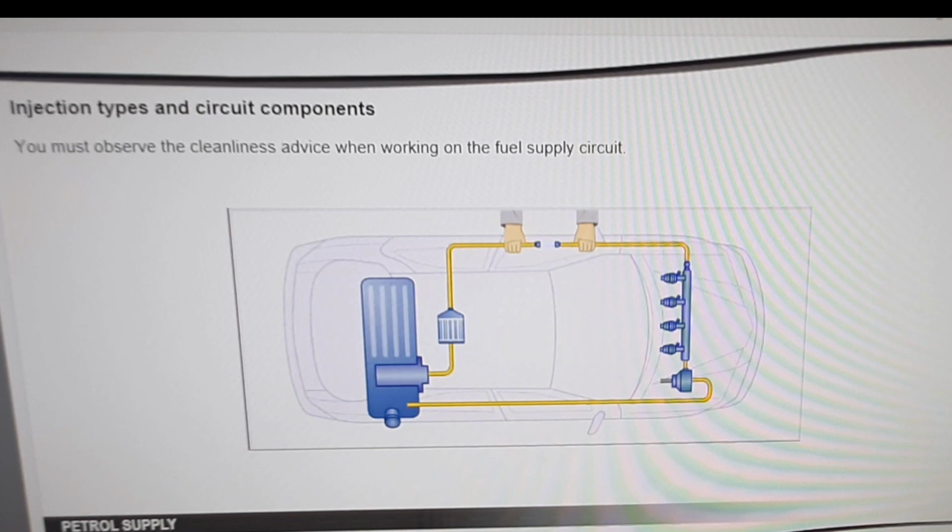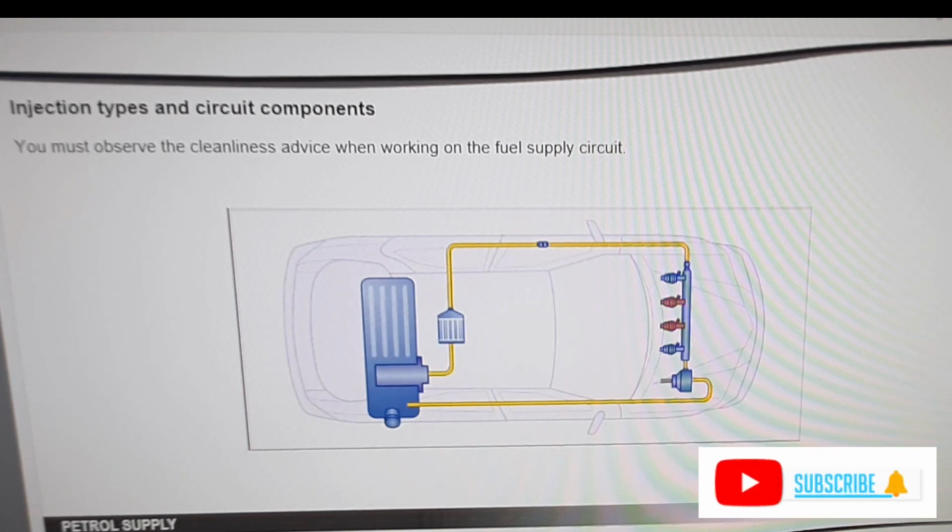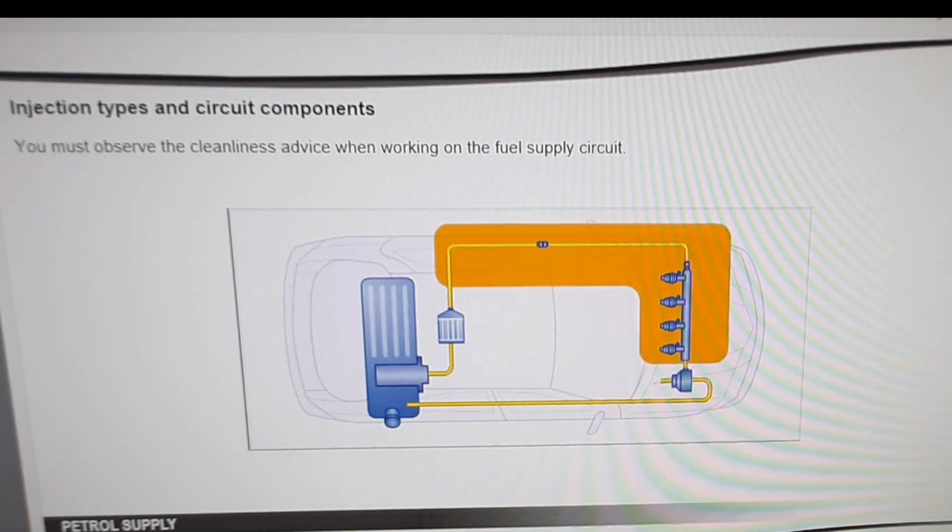The fuel supply systems are sensitive to impurities. Contamination by impurities may lead to a component sticking or leaking from its seals. The cleanliness principles must be applied from the fuel filter to the injectors. The cleanliness advice is described in the technical documentation.